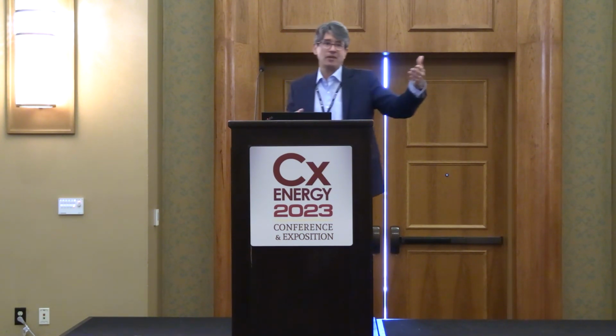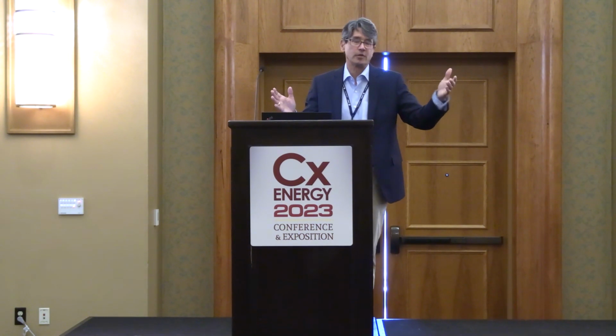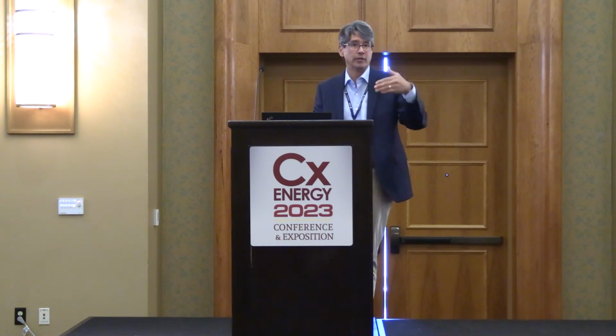So we look back and say, to avoid system effect, typically you need a good straight duct run. So you need a good place for a traverse. A good caveat, if you're looking at a situation where you've got some conglomerated ductwork, is making sure those people understand the energy cost impact they're going to have on their building by cramming all this into a mechanical room to get more square footage.